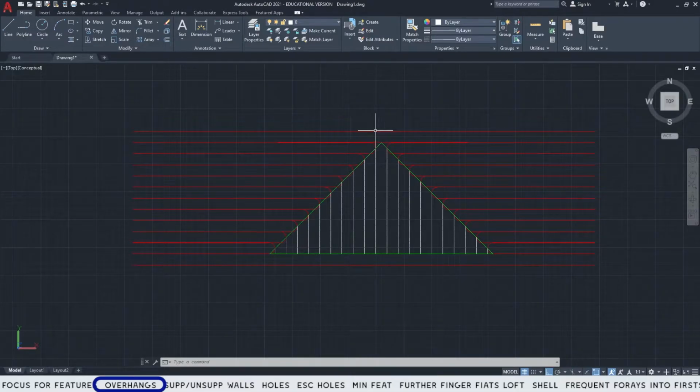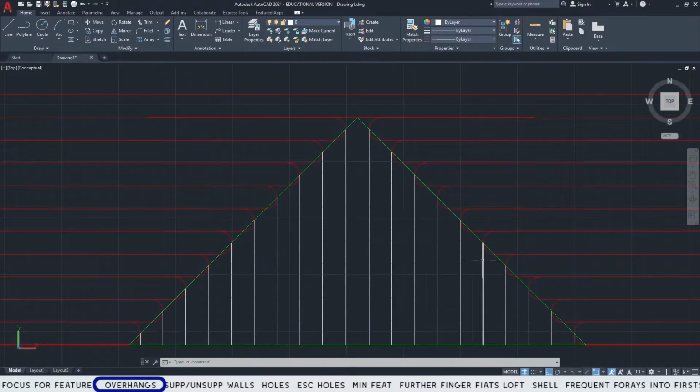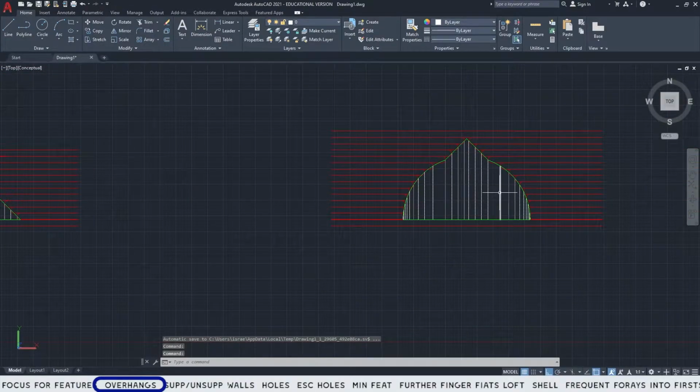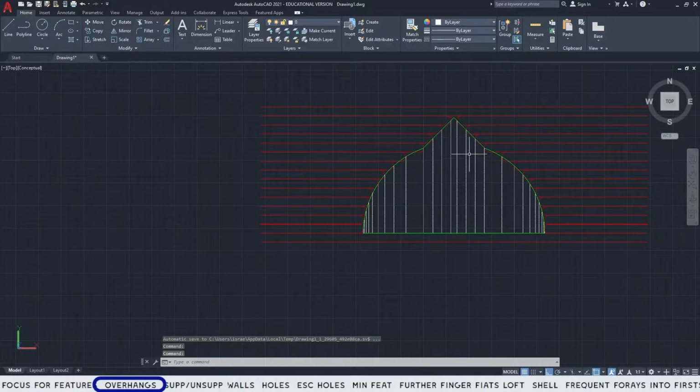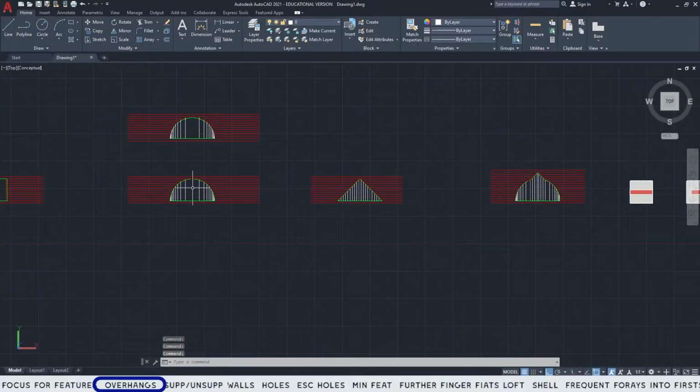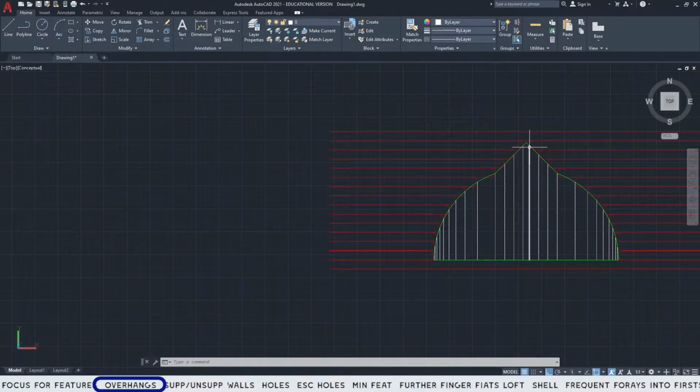I have created this corner here where there is a uniform overhang all the way across the board. This is a 45-degree angle, so I could print this with very little overhang so that supports aren't needed. So let's say that I did want to create something with a curved wall. I can put a little notch here at the top. It doesn't have to be as extreme as this, but you'll notice that this has a pretty wide gap right here at the top, but if I put a notch in here, you'll see that back again at 45 degrees, it's minimal enough to where supports aren't needed.